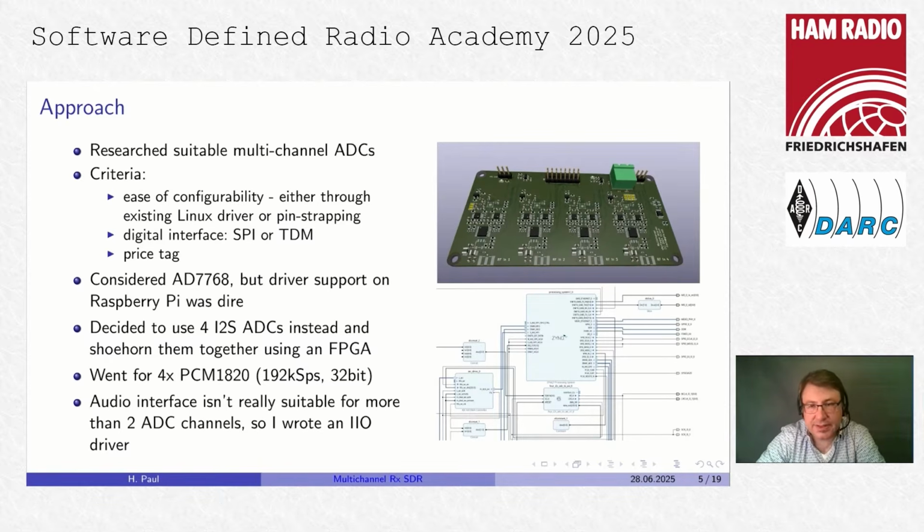Because stereo ADC, and so 4 times 2, 8 samples, and these are then just transferred via DMA into the processor core of the FPGA, and then everything is basically the same way I did it with my older SDRs I presented 3 and 4 years ago at the SDR Academy.